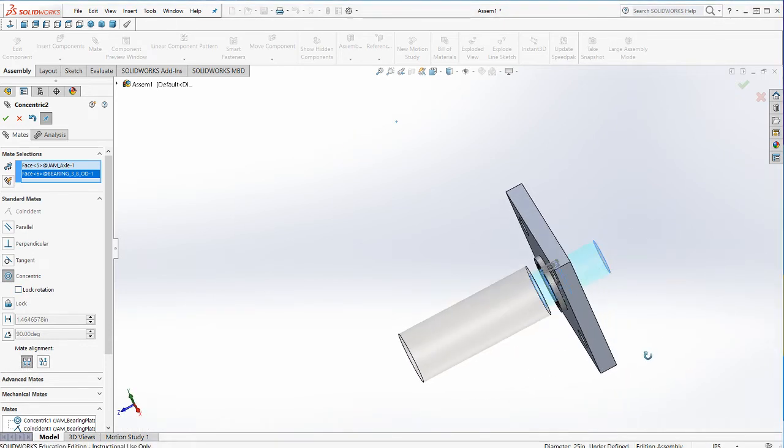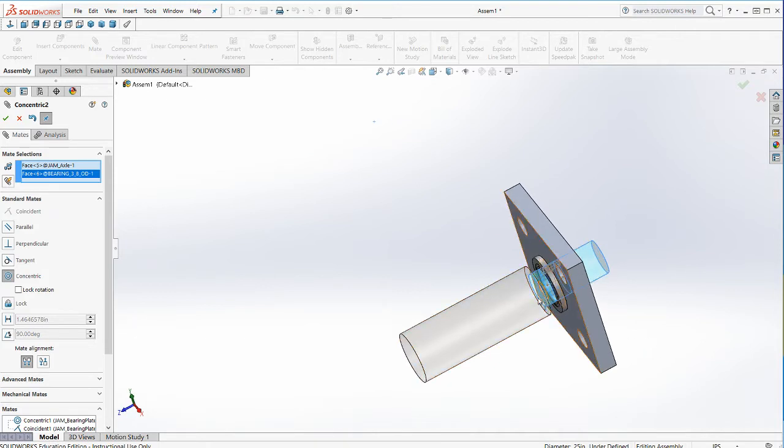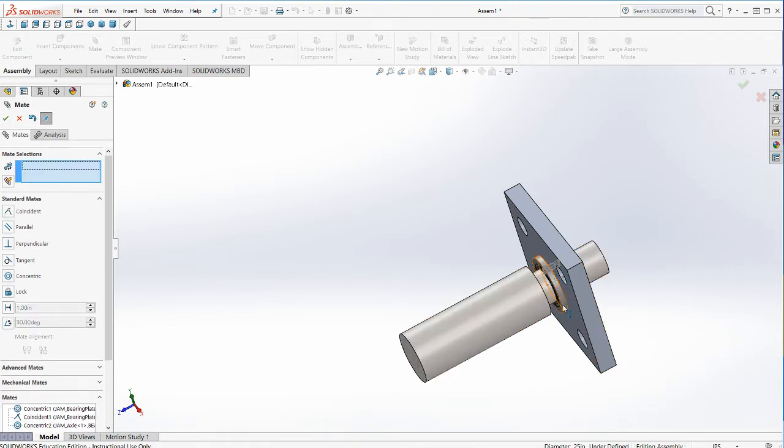It's, once again, arbitrary, but, well, in this case, it's not arbitrary. I should have this on the side that has the flange. Yeah, because it's resisting, if it's pushing on it at all, it's going to want to be on this side. So I hit the check mark to accept those constraints.